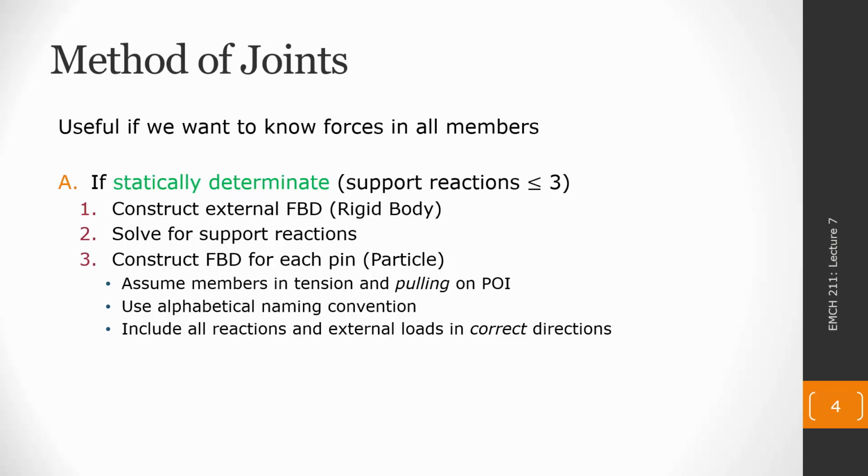Note, this is not talking about the members in the structure. We are always assuming tension, even if we figure out that something is in compression or several are in compression, we are still always going to assume tension in the drawings, and we use those FBDs to derive our equilibrium equations. Never redraw these internal forces in the members. The only thing you should draw in the proper direction, once we know the proper direction, is the external forces from steps 1 and 2.